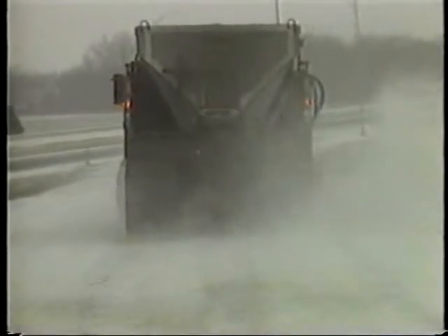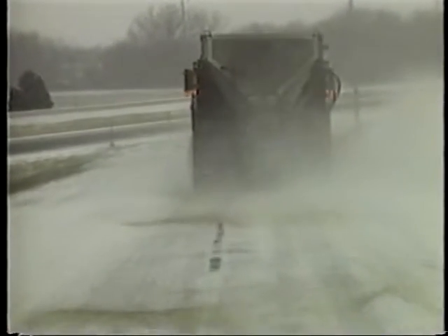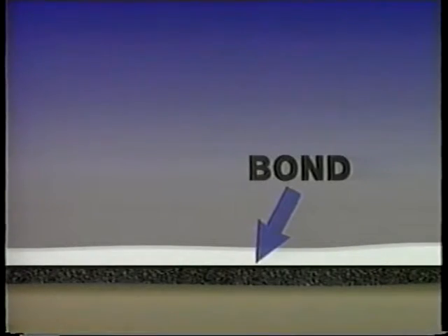Timing of chemical applications is critical. Dry, solid chemicals should not be applied on dry pavement because the particles can bounce off the pavement or be blown off by traffic. When applying dry, solid chemicals, it is best to wait until early in the storm, when the pavement is wet or when frozen precipitation has begun to accumulate. The primary objective is to place the chemical early enough to prevent development of an ice-pavement bond.